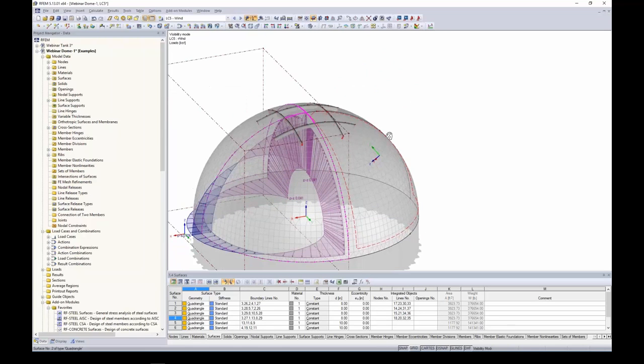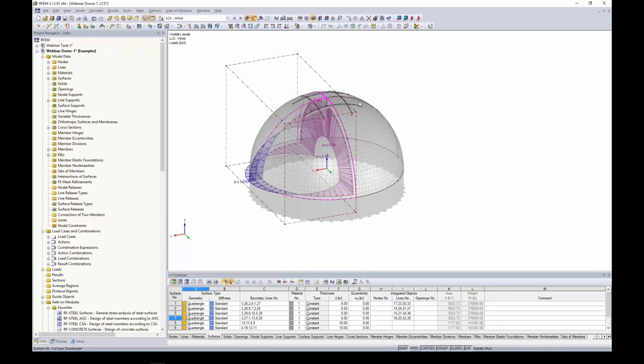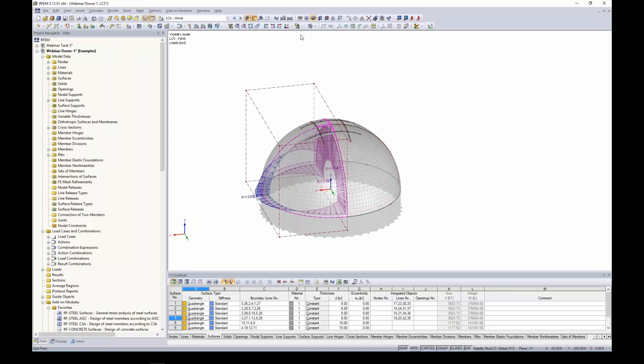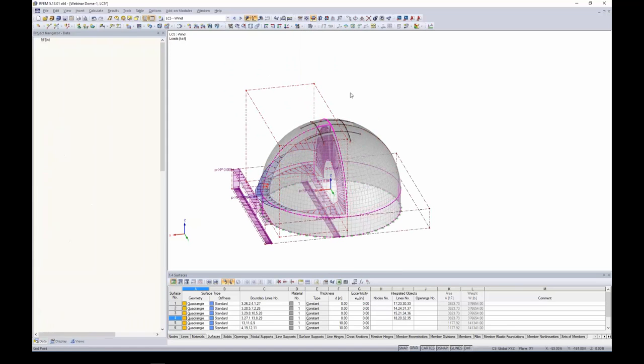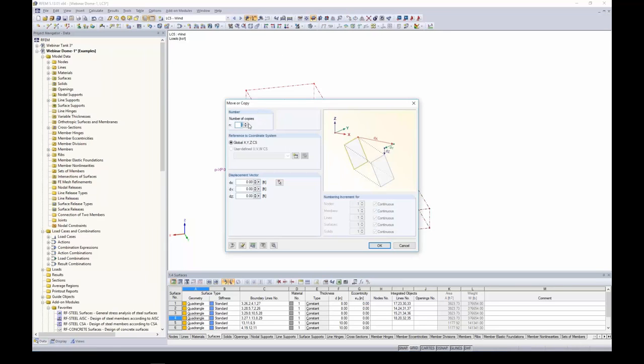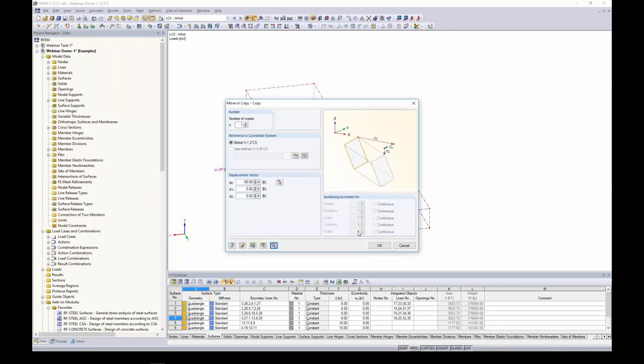Now as for the back of the structure, same exact concept, and a really easy tool to use is to highlight this rectangular load. Well, if I can select it. Okay, let's highlight this free rectangular load, and then I'm going to use my Move Copy tool. I'm going to create one copy, and I'm going to apply it in the negative 50 foot direction according to my global x-axis. Now I want to clear off the create surfaces between copied lines.